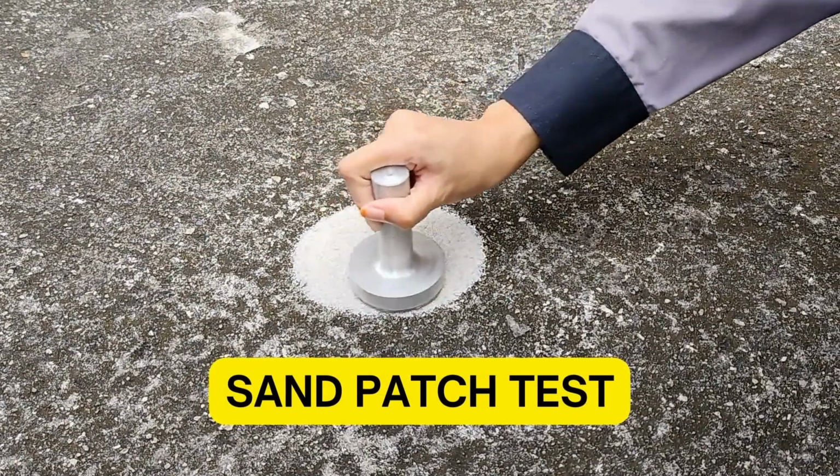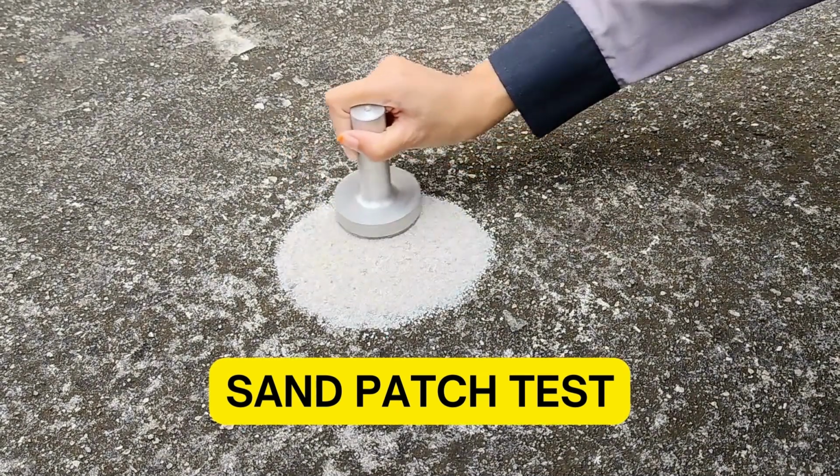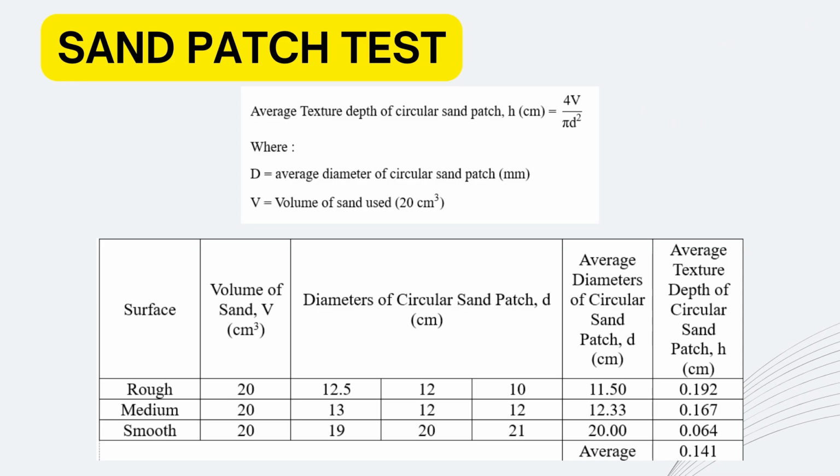Next evaluation was the sand patch test. This test evaluates the texture depth of the surface, which is crucial for water drainage and skid resistance. To determine the average texture depth of a circular sand patch, H is calculated with the formula H cm equals 4V over pi d squared, where d is the average diameter of the circular sand patch in centimeters and V is the volume of sand in